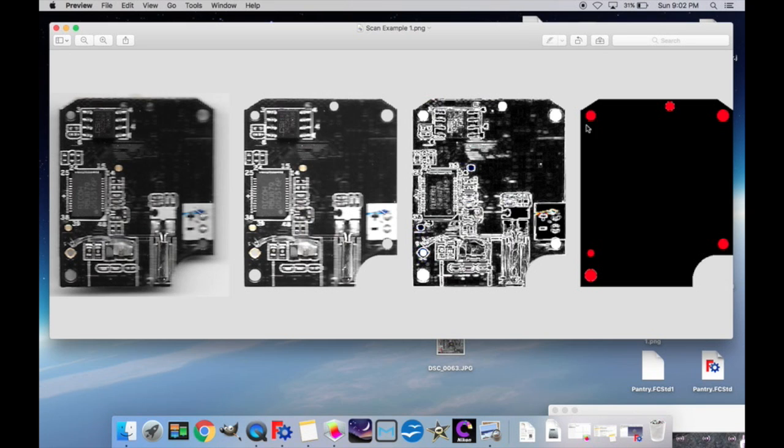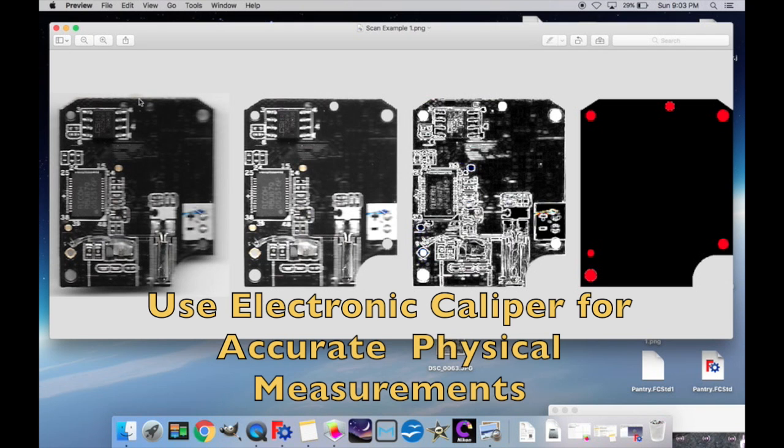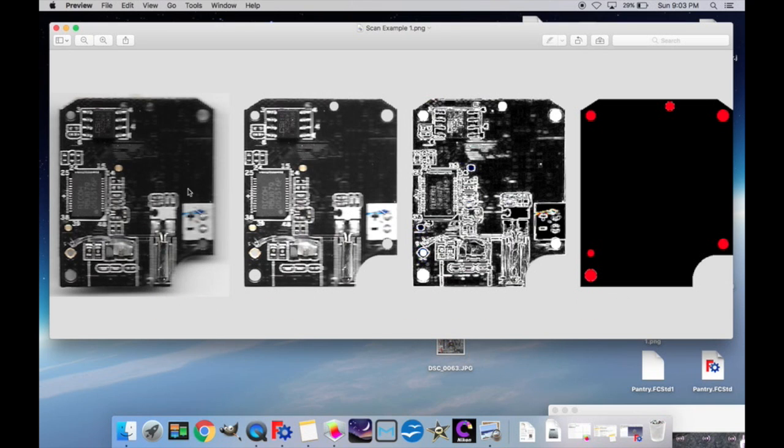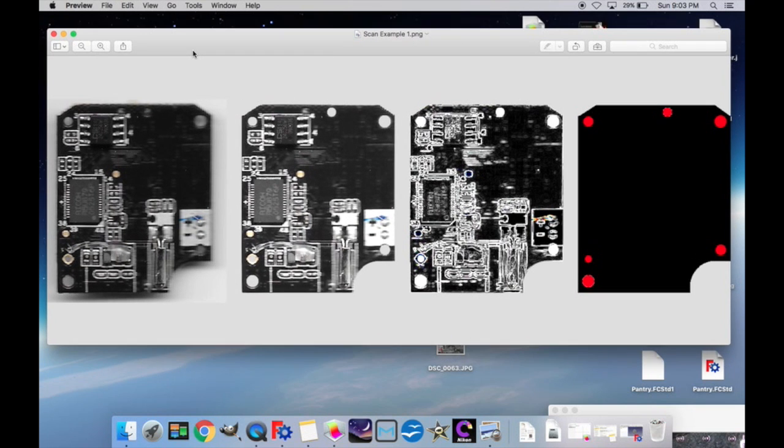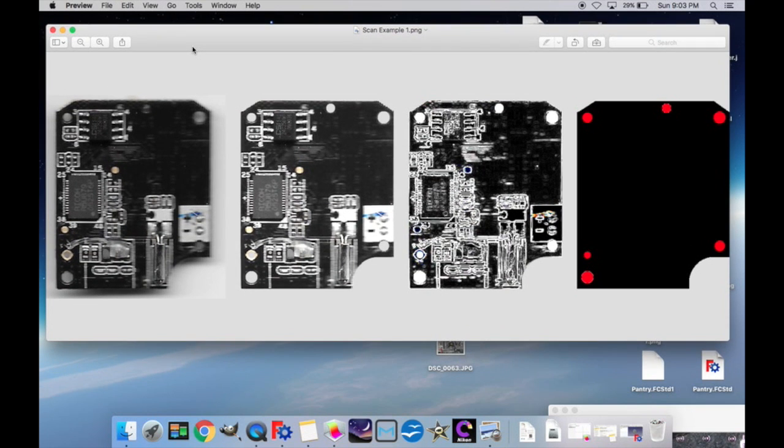And then from there you can make a tracing in a new layer of all the screw holes or the outer dimensions or whatever it is that you're interested in finding out. So the scaling ratio for an object like this works just like it did with the other one, only before you scan it or after you scan it, you measure its dimensions from either here to here or here to here, and then you just measure how many pixels are in that same space and find a ratio that way. So that's one useful way of being able to create an image of an object to work with.